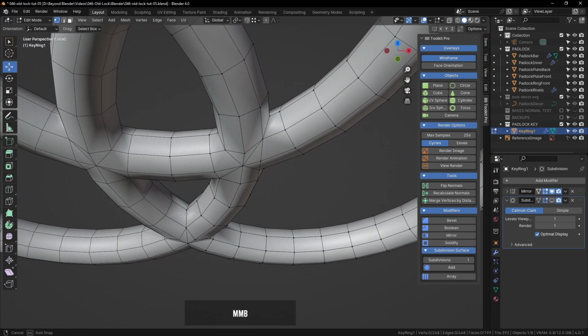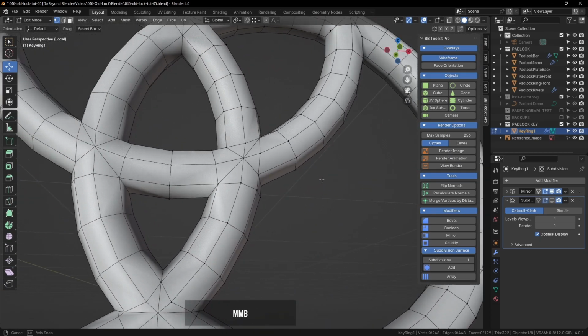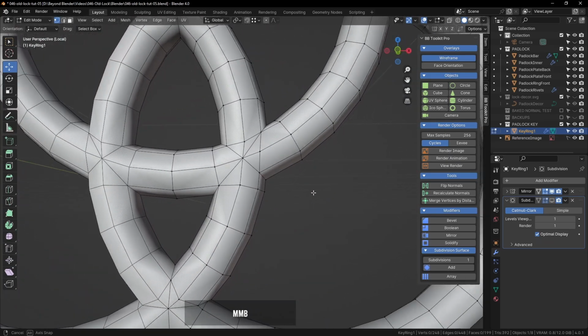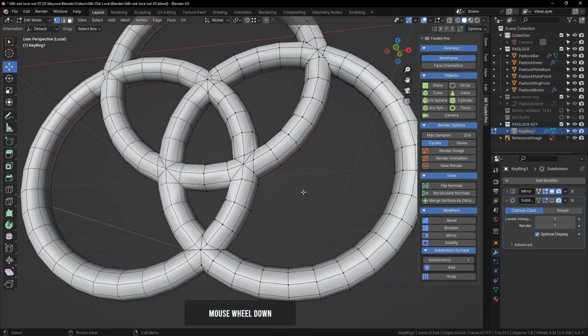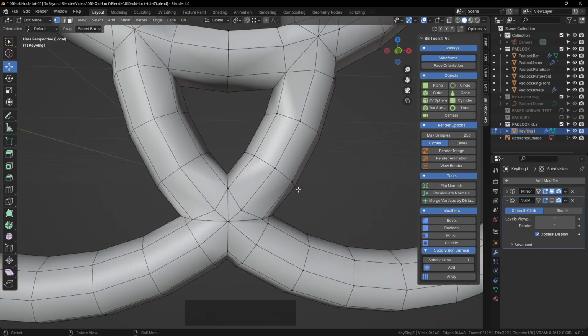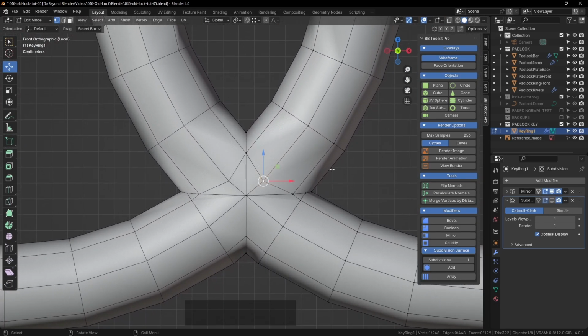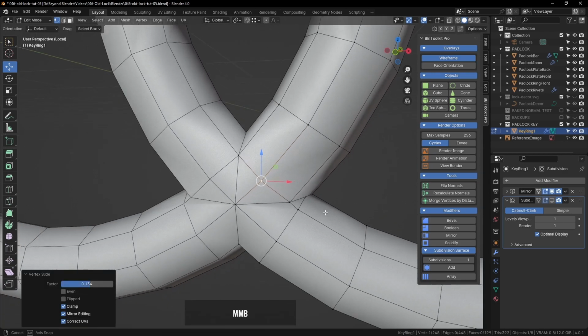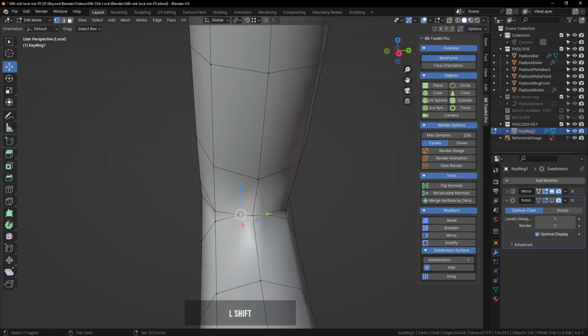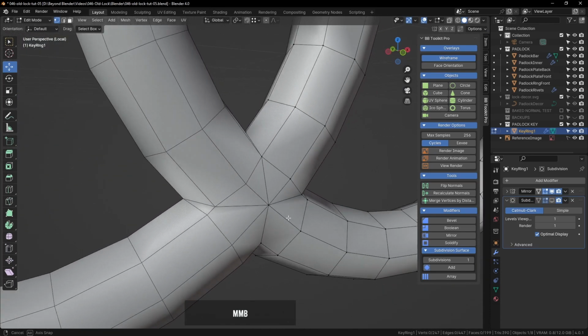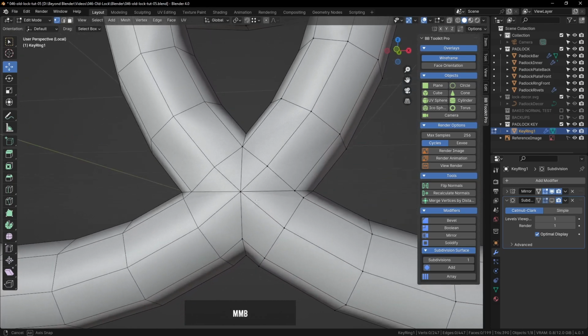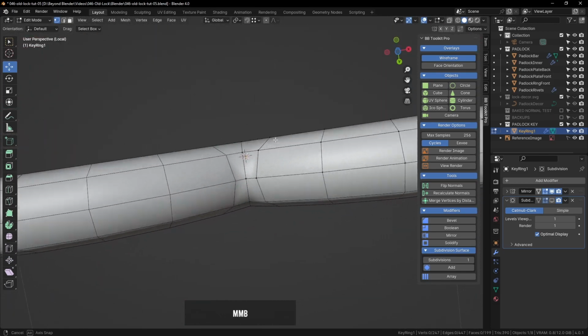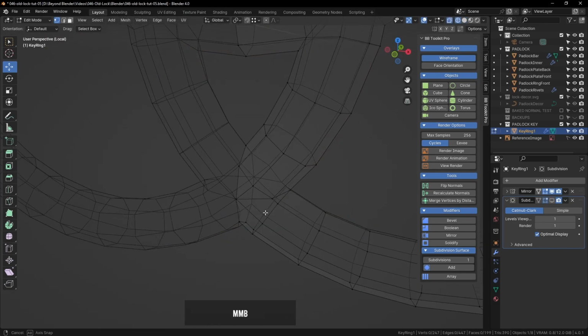There's one right there, we can do the same again. So click the vertex, press GG and slide it along the existing edge. As you can see, this is not difficult work really. Yes, it's tedious, granted, but it doesn't really take that long once you get into the swing of it. It's pretty quick. Unlike this video, sorry about that. Yeah, there we go, there's some more weird ones there. Let's merge that there. And we probably don't need these ones as well, but we'll come back to this a bit later on.